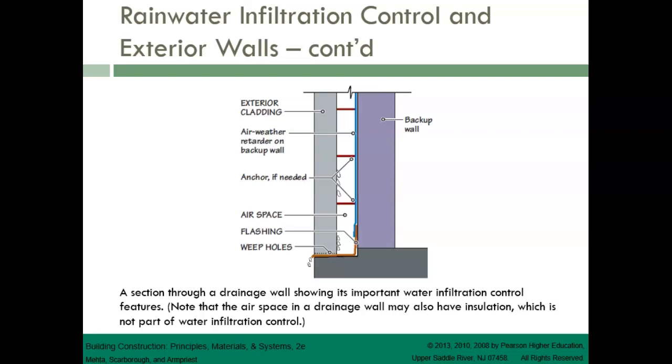An example of a face-sealed wall is a CMU or concrete wall system with an applied water-resistant veneer, such as EIFS or stucco. On the other hand, an example of a barrier wall that acts as a reservoir is a porous masonry or concrete wall that is so thick that any absorbed water is unable to migrate into the wall's interior surface. The thicker the wall, the larger the reservoir. In this type of wall, only the outer layer of the wall gets wet. Even during a long rainy spell, given a long dry spell, the entire wall will dry again.